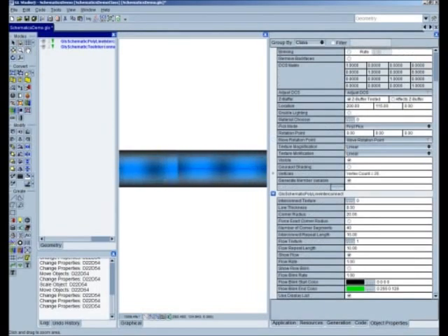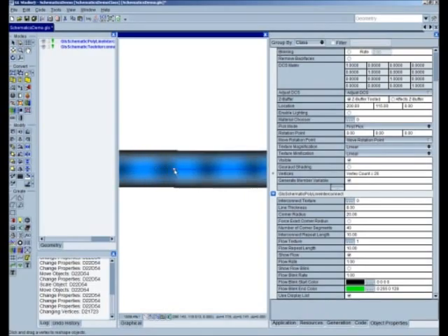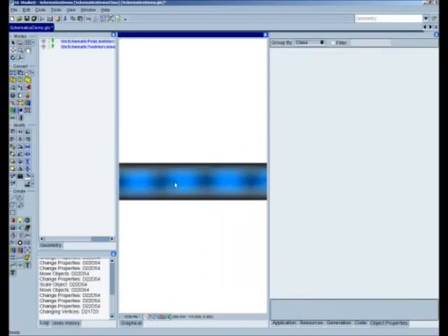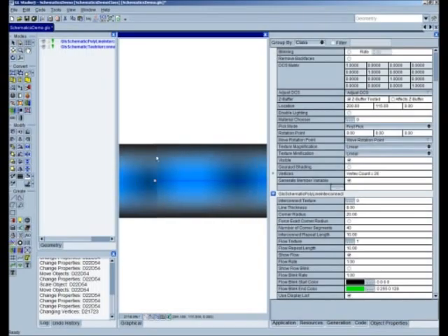Selecting the Polyline Interconnect and going to vertex mode, we see that the end vertex for the polyline actually extends well into the T. Adjusting it, we can get closer and closer. The closer you get, the more that joint disappears. So, assuming my dexterity is up to par, let's see. Looks like we've got that just about where we want it. The periods are lining up.